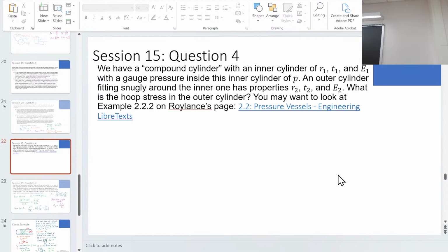Y here is H. So MY equals FLH. M is FL, right? Force times length is moment. And Y here is height. Oh, so it's about the Y. That's the one. And over 2I, I is BH cubed over 12, times 2, it's 12 times 6. And with algebra, you get H over 3, I think it was.